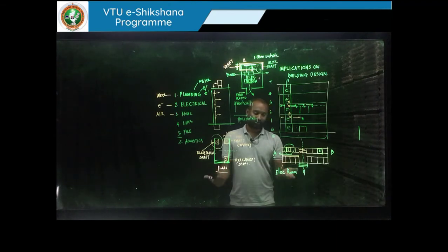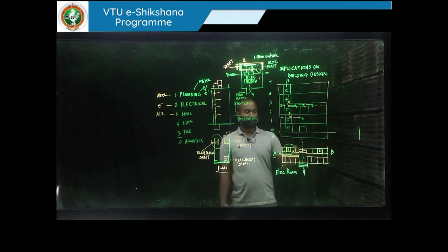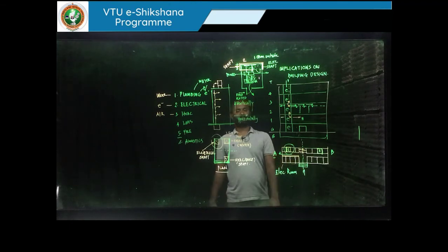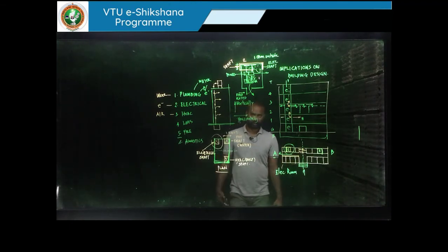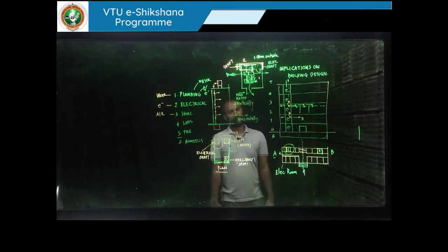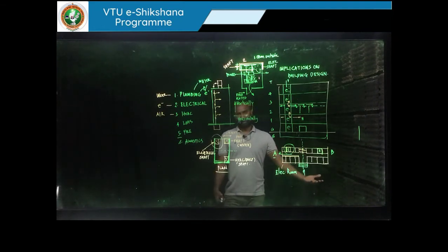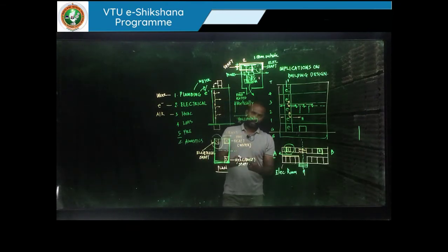It can be as well as 4 zones, or it can be just 1 zone where you have this one shaft and the electrical room communicating vertically and horizontally across all those rooms and floors. There is so much possibility. Of course, like your architectural finishes, there are so many factors playing a role here. Depending on that, we can have several strategies. But again, remember this: shaft location, electrical room location, and the door opening.